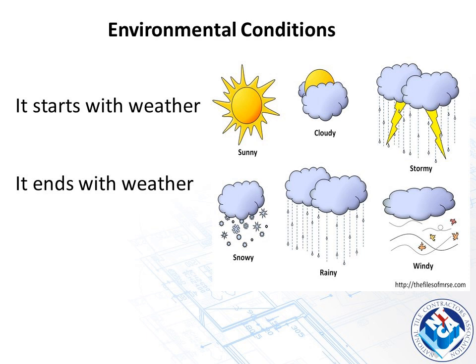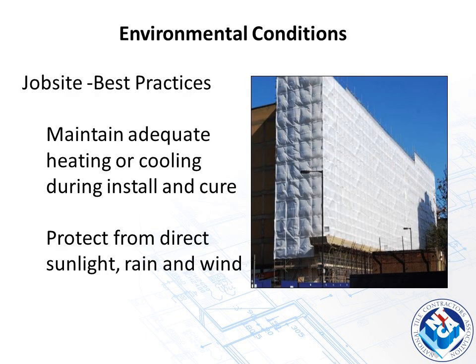Let's talk about some of the other conditions. Windy. When we're doing exteriors and we're trying to make sure the mortars don't skim over, an extended open time mortar can be very, very beneficial, especially if you're in windy conditions. But more important, just protect the installation.